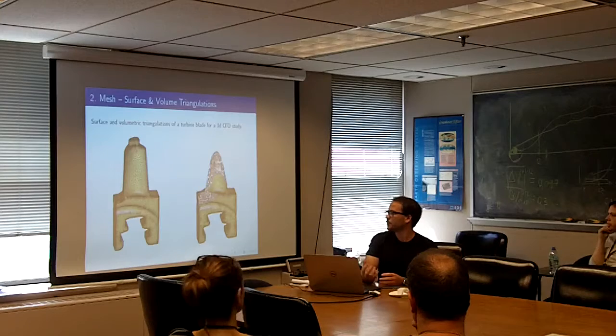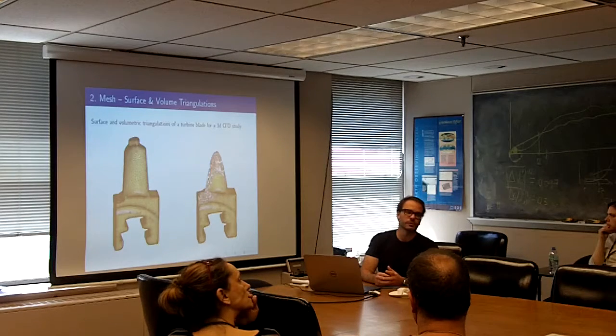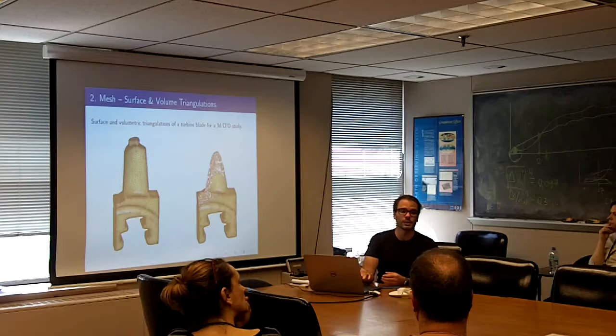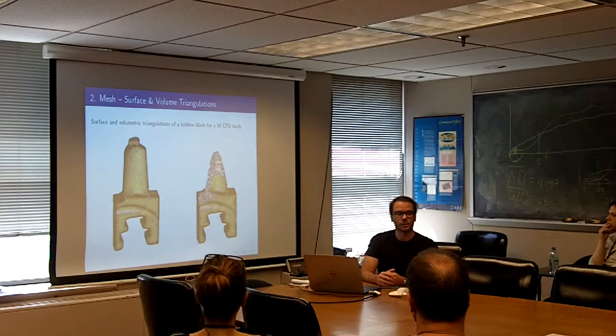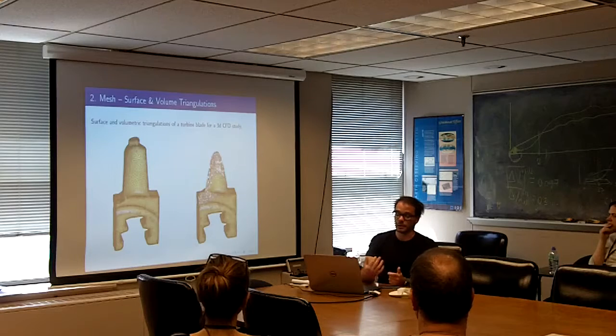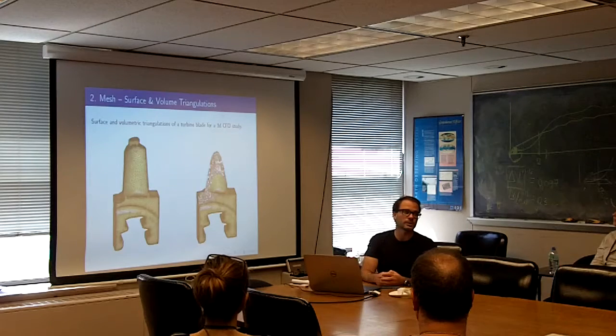And dealing with the way that the refinement algorithms work in the fully 3-dimensional case can get extremely complicated. Even though it's something that needs to be used in lots of different forms of numerical analysis, the fully 3-dimensional problem is still actually unsolved theoretically. So no one has yet proposed a particular algorithm that can guarantee a lower bound in terms of the angle between the faces of tetrahedrons.